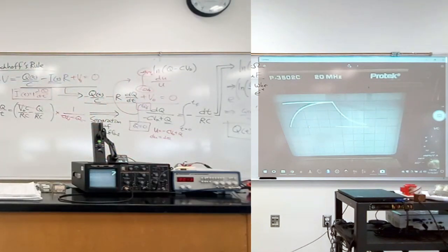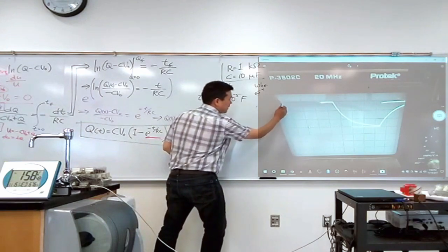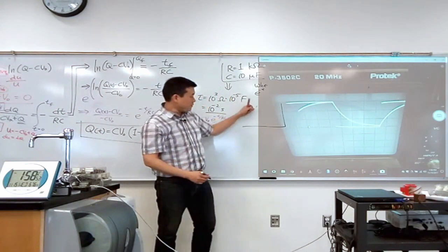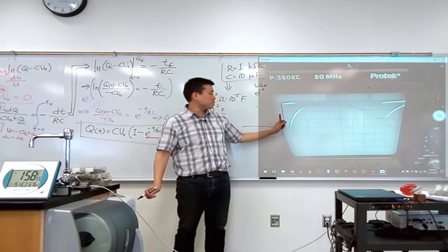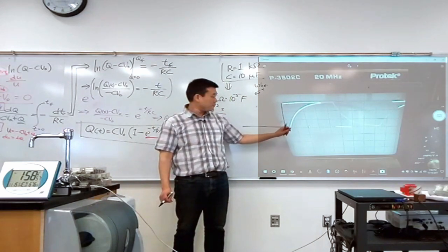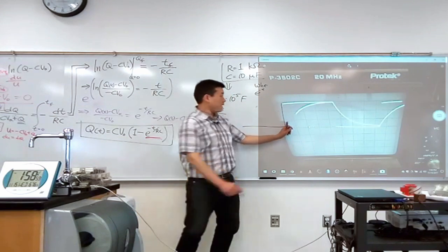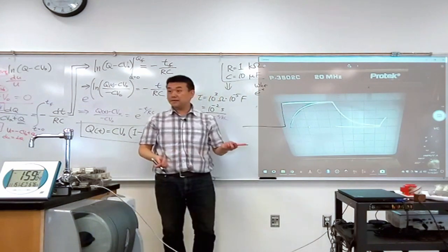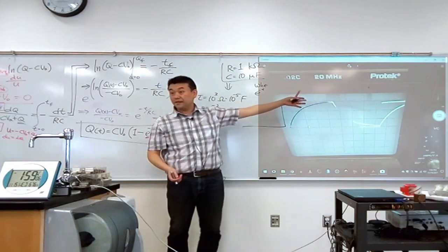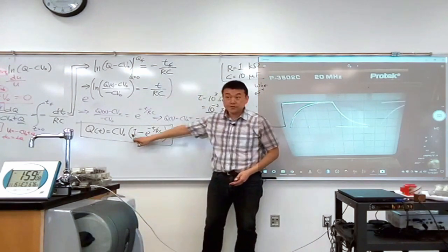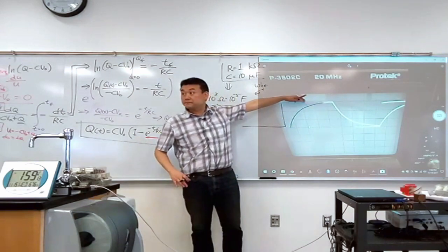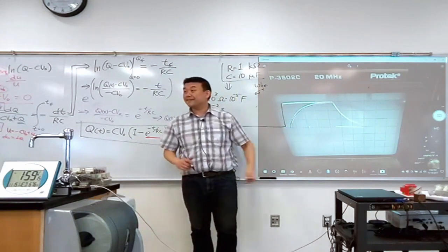So what you have to imagine here is on the left-hand side, there's this portion of the square wave. At the end of this square wave, I more or less discharge the capacitor. So you're starting out with a 0 charge on the capacitor. And this curve here, it's not exponential rise. What it is is flipped over exponential decay, subtracting from this asymptote value of 1. Okay. So that's what you get.